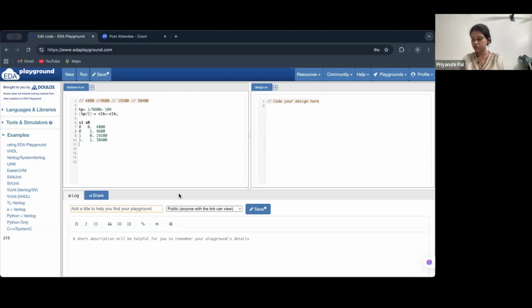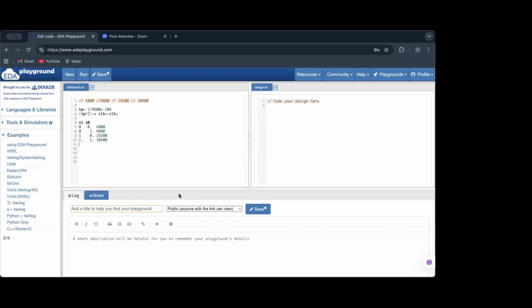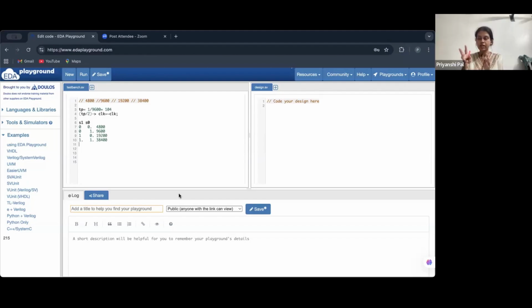Okay, ma'am. First we'll have our starting condition, which will be sent by the master to the slave. The slave will receive that starting condition. Then the master will send the address of the slave which it wants to access, and the slave will receive that slave address, and if it's valid, it will send the acknowledgement as 1.